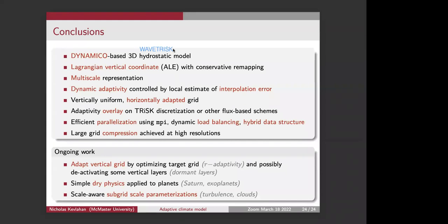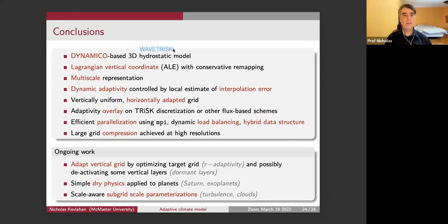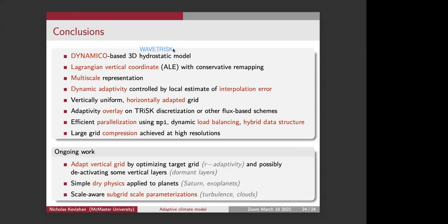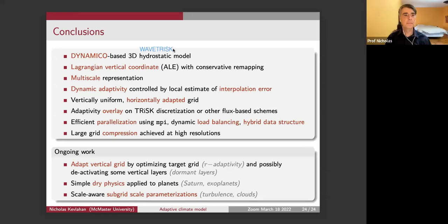And for the time discretization, do you use the standard Crank-Nicolson or fractional theta scheme? We typically use a Runge-Kutta scheme, a third or fourth order Runge-Kutta scheme. And when we do the barotropic mode splitting, then you have a special scheme so you can harmonize those two modes, the fast mode and the slow mode.